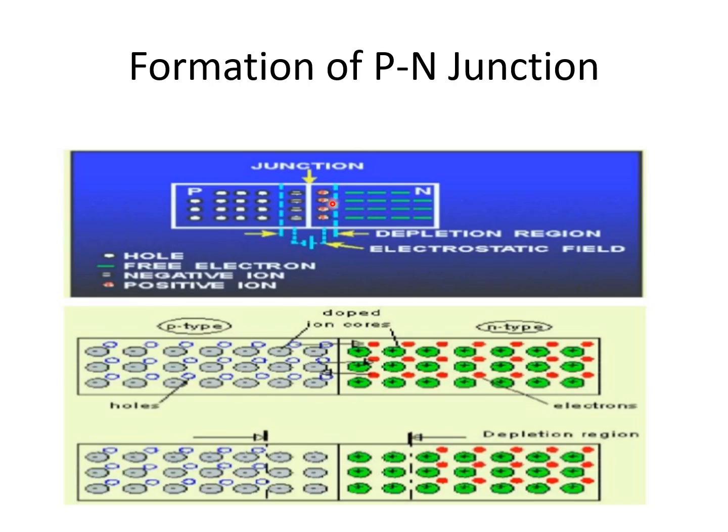So these electrons will move across the junction and combine with the holes, forming immobile negative ions. The holes in the p-type will move towards the n-type material and will form immobile positive ions. These immobile ions will create the depletion region. Depletion means lack of charge carriers.